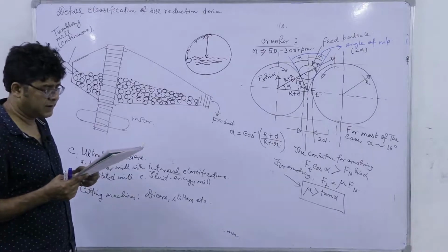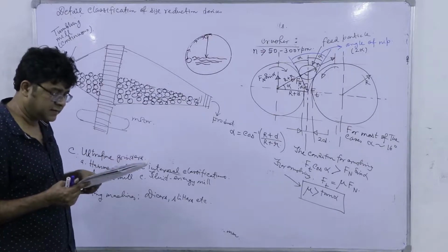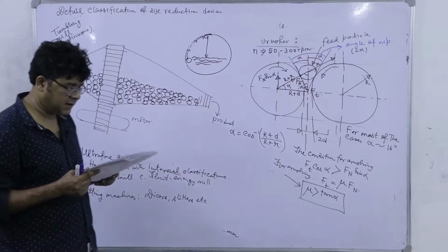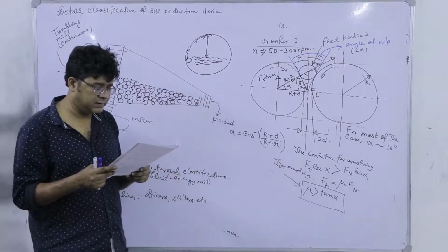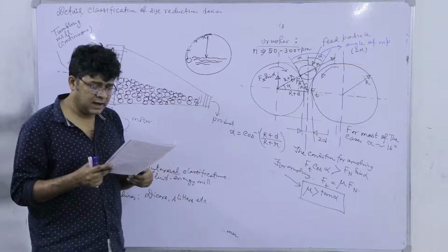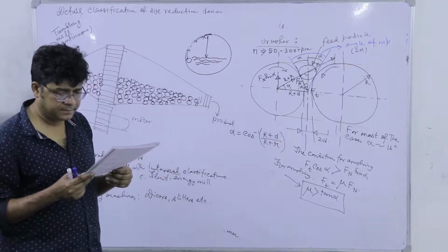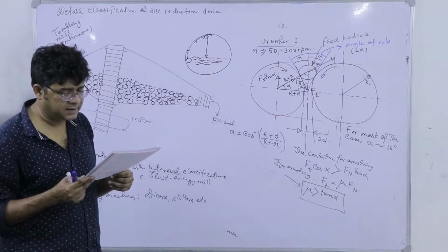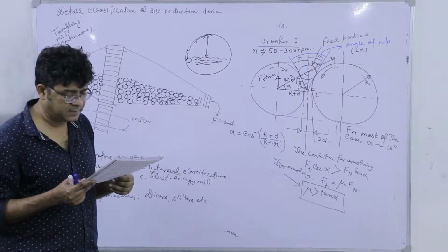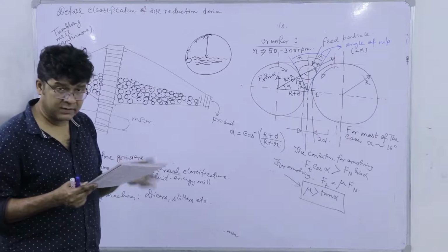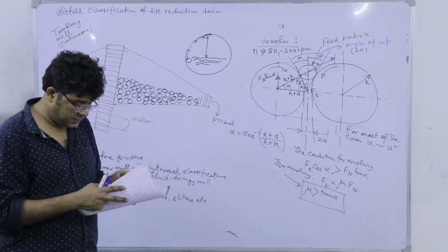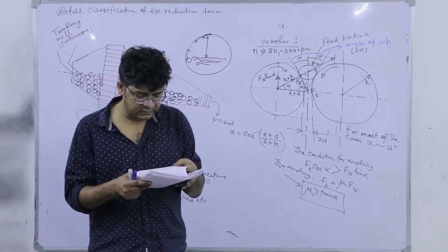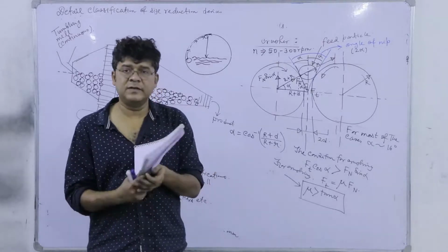When the mill is rotated, as I have stated, the faster the mill rotates, the faster the balls are carried up inside the mill, and the greater power is consumed. The added power is profitably used because the higher the balls are when they are released, the greater the impact at the bottom and the larger the productive capacity of the mill. If the speed is too high, the critical speed, the speed at which the outermost ball loses contact with the wall of the mill, depends on the balance between the gravitational force and the centrifugal force.